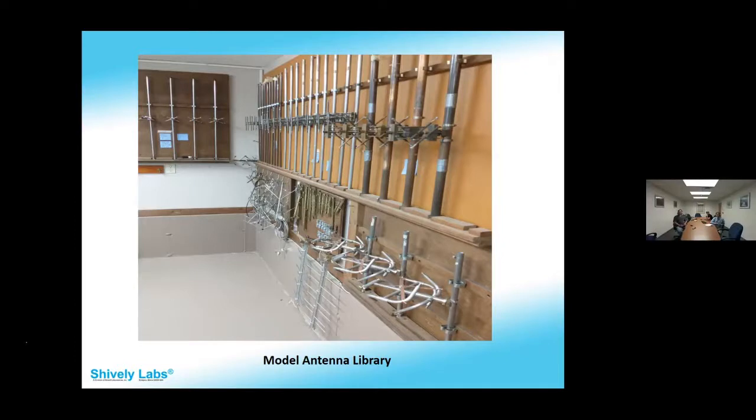Yeah, I can see why that could have advantages, because it really depends on the beam width. They're reciprocal devices, so the beam width of the transmit, or what should be the receive antenna. I think what you're referring to is probably trying to illuminate the model antenna, the actual radiator, with a pencil beam, a narrow beam width source, so that there are fewer reflections.